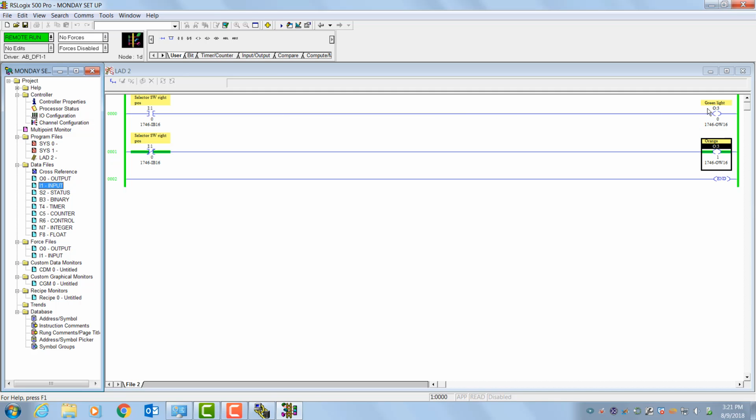So this output is not true. And the examine off instruction says a 0 makes it true. And now I can verify for you that the orange light is lit. And by going back and forth between these two positions, these two different instructions manipulate these outputs.